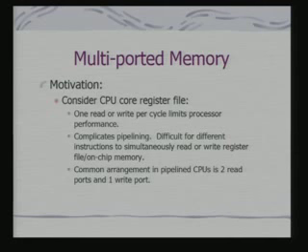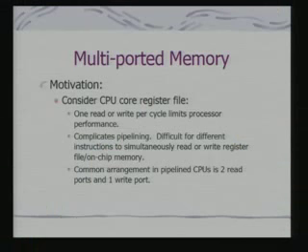It also complicates the pipelining, because it becomes difficult for different instructions to simultaneously read the register file or on-chip memory. So, a very common arrangement is for pipelined CPUs to be provided with 2 read ports and 1 write port associated with the memory.